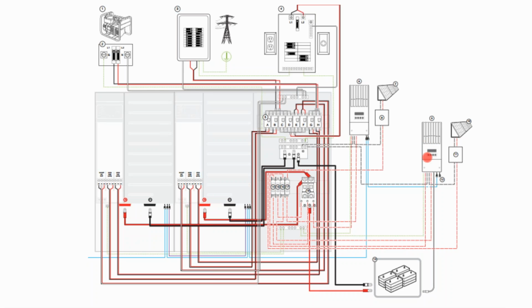And so our charge controller is taking the variable voltage from the array, fixing its output, and bringing it down to the voltage of our battery bank, which in the lead acid arena may be 48 to 60 volts, although they can go higher. There's really no reason that a battery bank can't go higher.